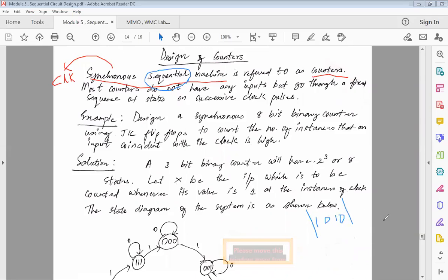If this is changed, let's say I have two zeros and two ones, even if I reorder them, here also it is two zeros and two ones, but I cannot say that this is a sequence, right? So the sequence actually matters, one after the other. Exactly one after the other, I need to have those particular bits. So I can say that this sequence is good, which means detected, and this sequence is an incorrect sequence, even though it has the same number of ones and zeros.